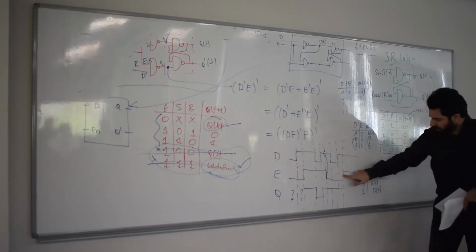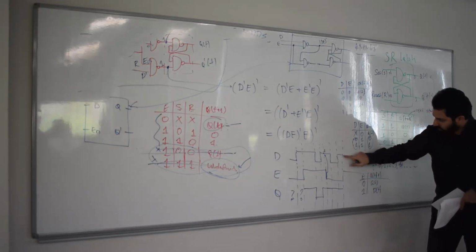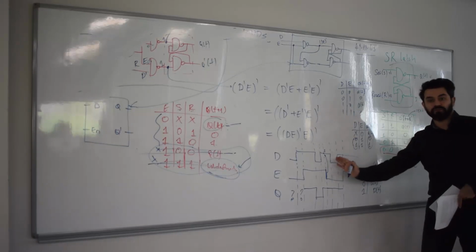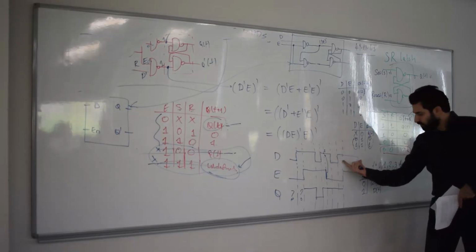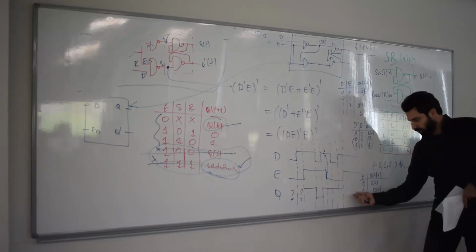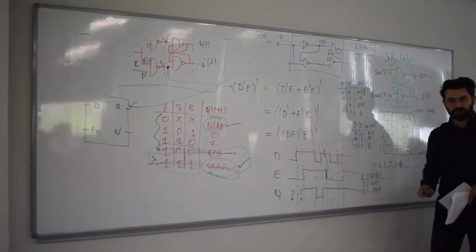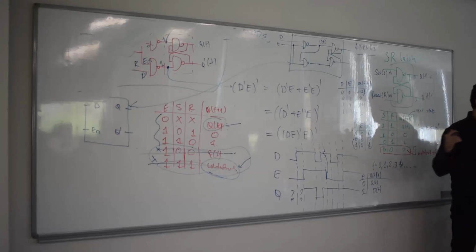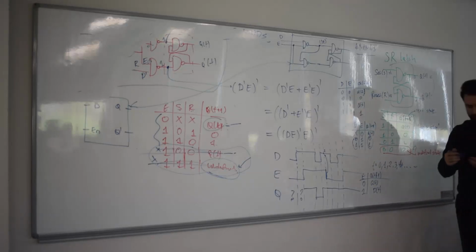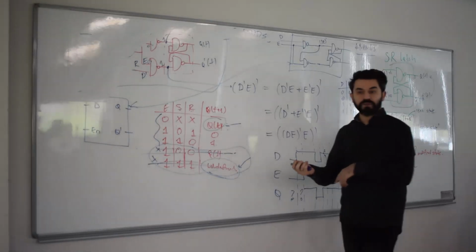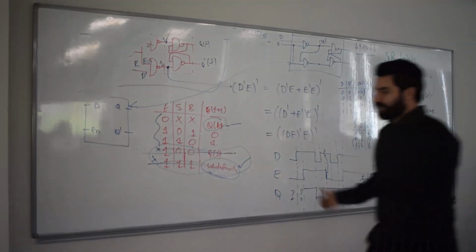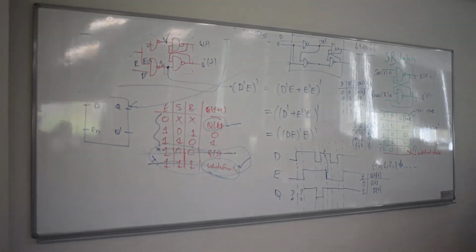And finally, of course, all of a sudden the enable becomes 1. That would start copying D again without looking at what the previous value was. So you see it's all 1, so it's going to copy all 1 here. Now, coming back to my previous comment, I said that noise is also copied, correct? So let me show you an example where the D input could be noisier.